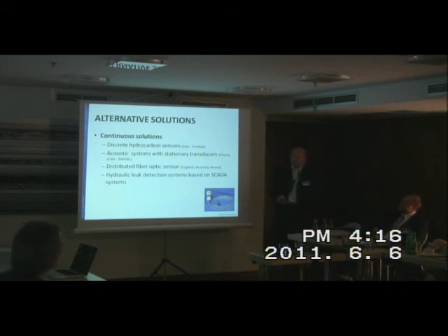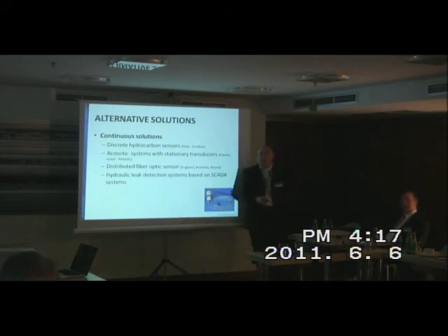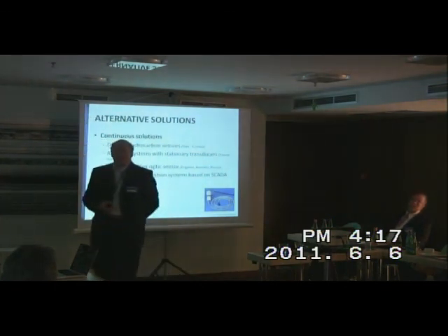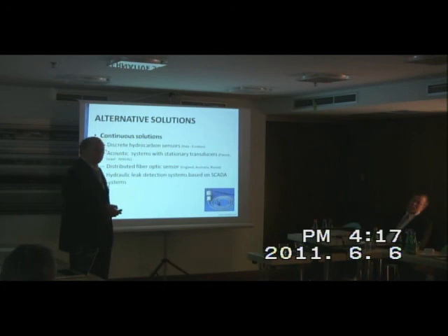There are other types of solutions, like discrete hydrocarbon sensors, acoustic sensors, fiber optic sensors, or leak detection systems based on scanner systems. Searching on the internet, you can find hydraulic leak detection solutions based on SCADA systems, but these systems are basically software, only the central part. They use a normal pressure transmitter for this scope, yes? Do we have a comparison of our system against these systems? Vis-a-vis advantages, disadvantages, have we made any comparative statement?